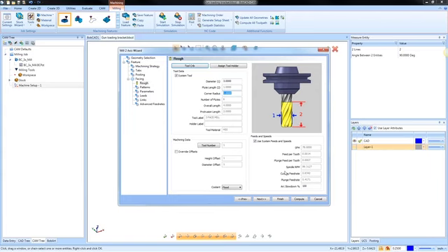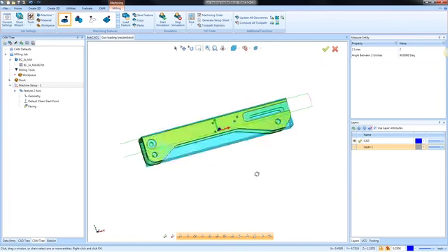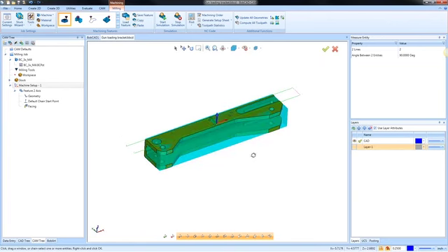All right. Now, there are some speeds and feeds being calculated for me. This is based off the material that we're using, and it's also based off the tool that we're using. You can override this. You can just come in here and type in the surface footage and chip load that you want, or you can just type in the speed, your RPM, and your feed rates that you're going to cut at. Okay, so really easy. You can just type in what you want there. For us, I'm actually going to just compute the defaults at this point. And by computing the defaults, we're going to see some toolpath on our screen.